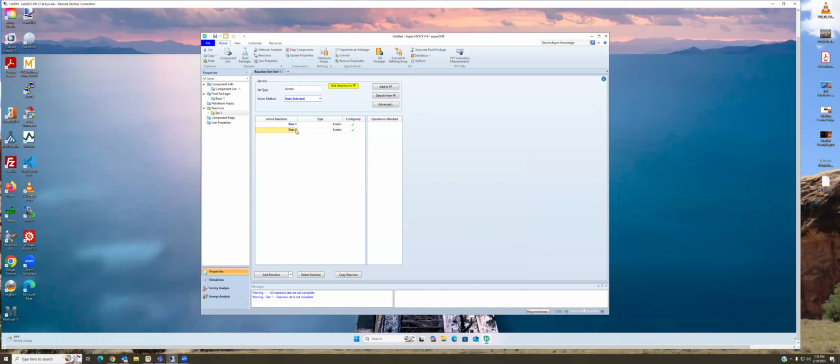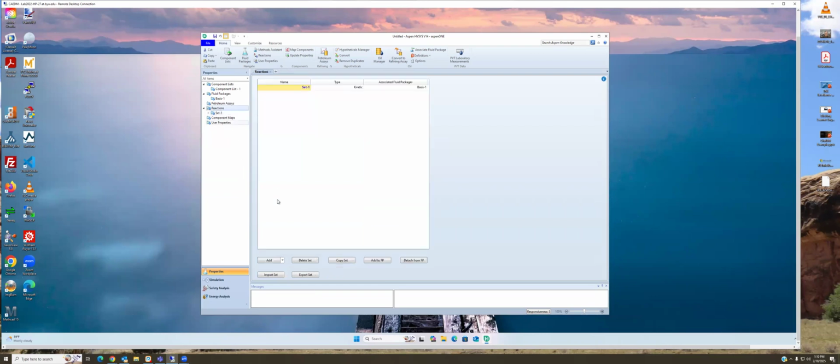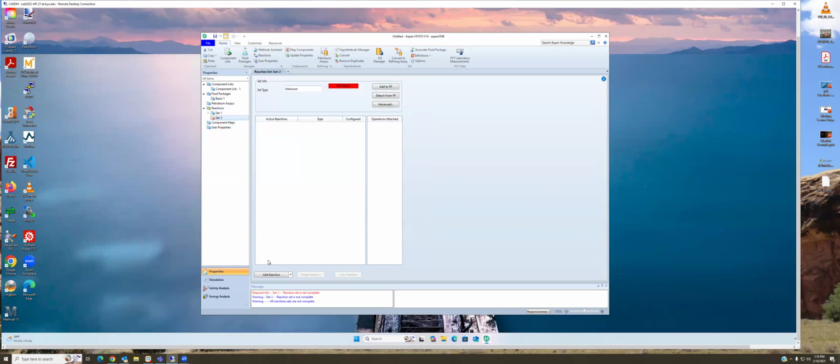And then the last thing we need to do with these reactions is add them to the fluid package so that the thermodynamics and the kinetics can all work together in the simulation calculations. Okay, so that's the first reaction set. Now we need to add the second one.